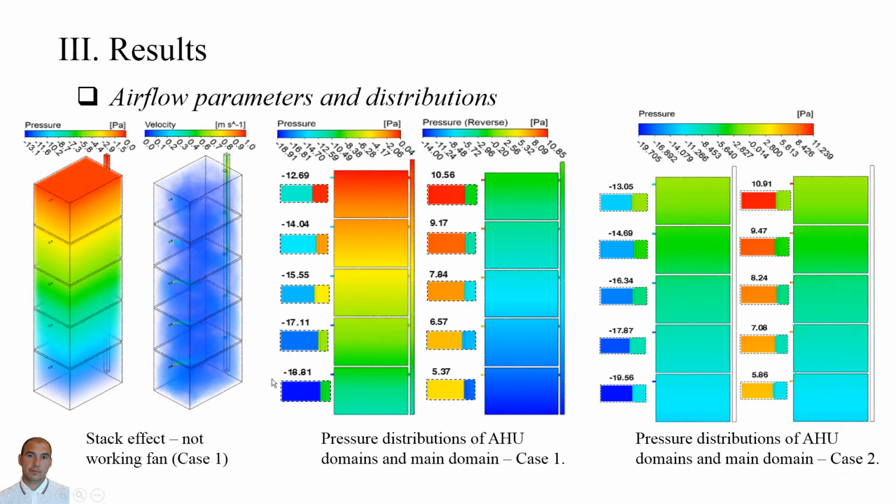The distribution shows the difference between the internal and external pressures for each room of the building, and the fans pressure jump for two operation modes, supply and exhaust airflow. This pressure difference leads to different airflows for two opposite flow directions at the different level in the building.